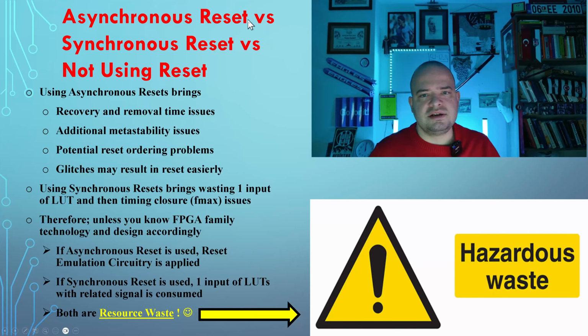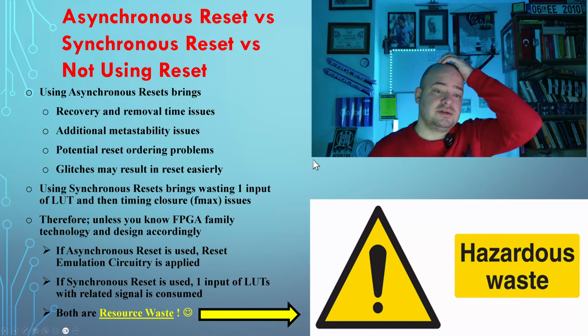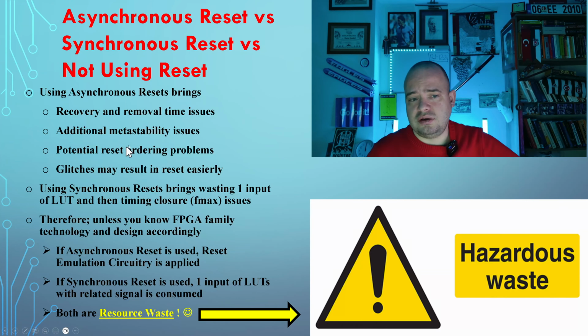Another slide regarding asynchronous reset versus synchronous reset versus not using reset. Using asynchronous reset brings recovery and removal time issues, since you are using asynchronous control input signals, additional metastability problems, and potential reset ordering problems, as we see in the cascade resetting issue in that RDC slide. Actually, the order of those resets matters a lot. You need to take additional care regarding those.